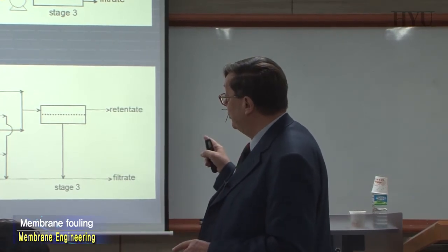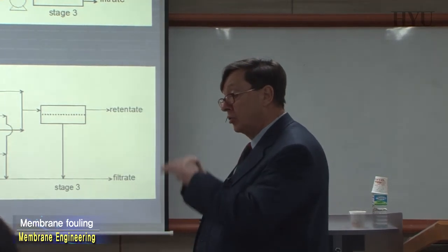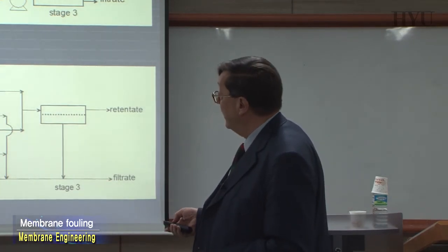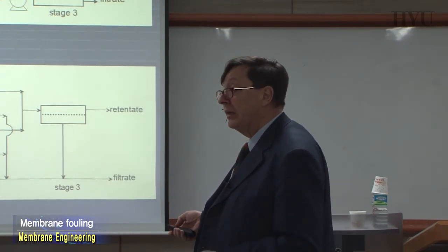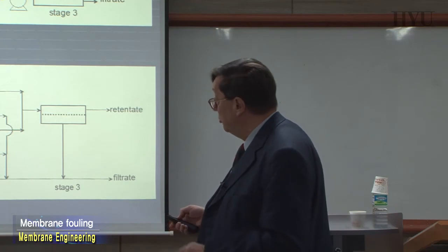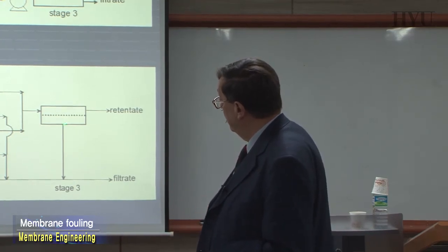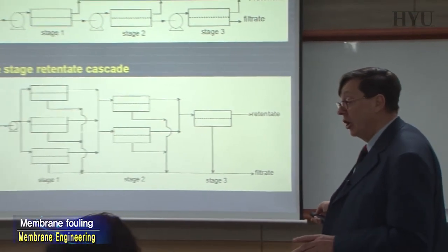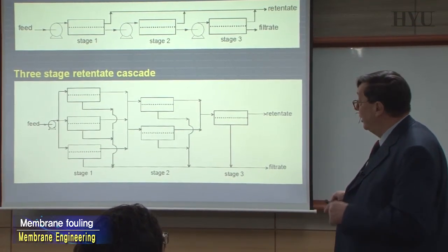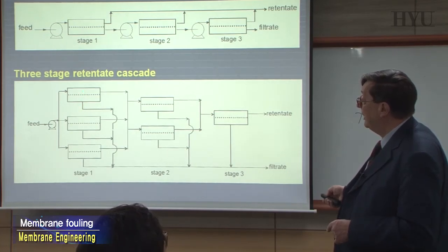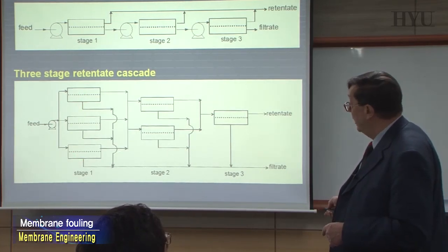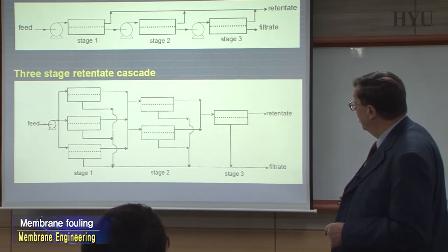And the motivation for doing this is, on one side, to control the overall capacity, not related to one single module, but the other one is to control the capacity, reproducing for a single module the same performance that will be present in all the others. Not easy. If you don't do this, you can have a nice, clean transmembrane flux here and big fouling here.